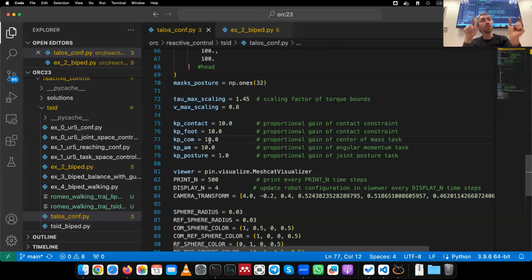And it's the feedforward that kills the delay, because if you're working in feedback, by construction, you're going to be delayed with respect to the reference, because you're only able to act to correct it after you see an error. And so having a higher gain means that the feedforward is smaller in relative terms. So it makes sense that you're able to keep up with the reference thanks to the feedback, and that introduces a delay in the system. So yeah, it's a good observation. I didn't notice.